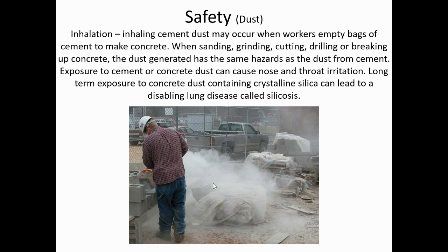So when you're working with concrete, you should be wearing some kind of dust mask. You can see this gentleman there is wearing the hard hat and the dust mask. A lot of times they wet it down so that you don't get that dust flying all over the place. But working with concrete, especially long-term exposure, you definitely want to protect your lungs.